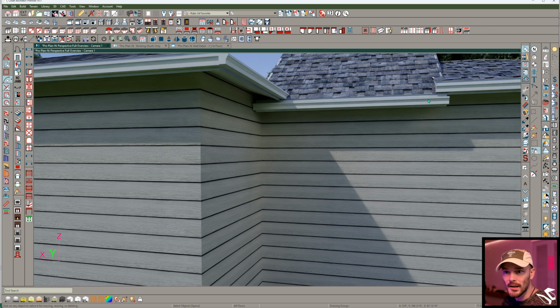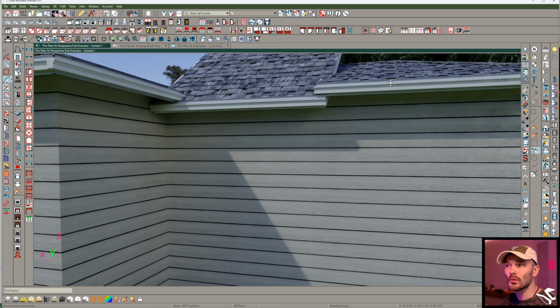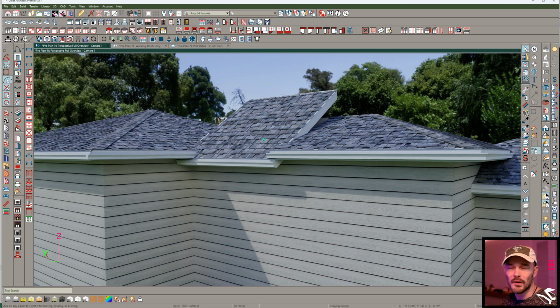That we're building off that same plate height, because we wouldn't go through all the trouble of changing all these wall heights, building custom wall heights, slowing our production way, way down just to get this effect. No. Instead, all this is telling us is we're building to the same plate height, but we've got a different pitch roof. Or we have a different roof assembly. There's different thickness to it. Or we're matching up with some element somewhere else. But that plate height still remains the constant.